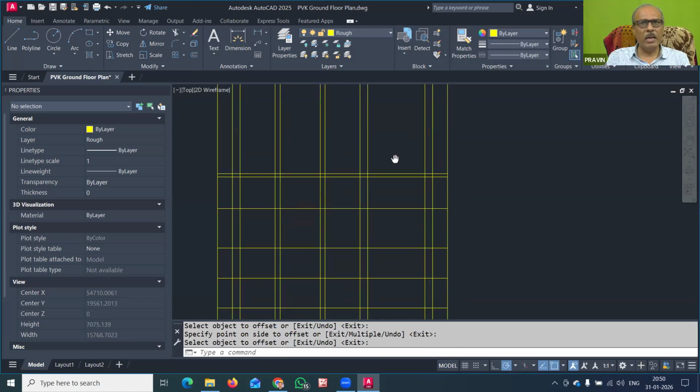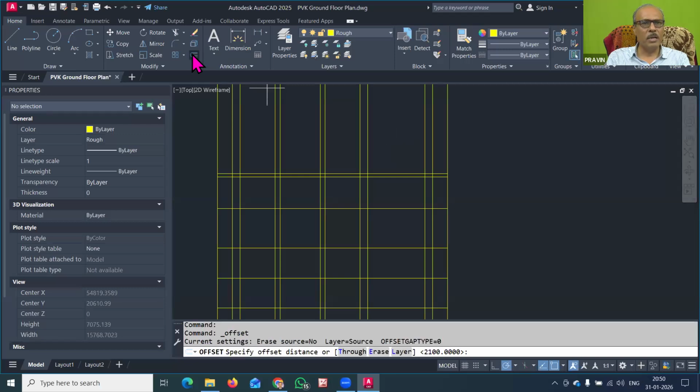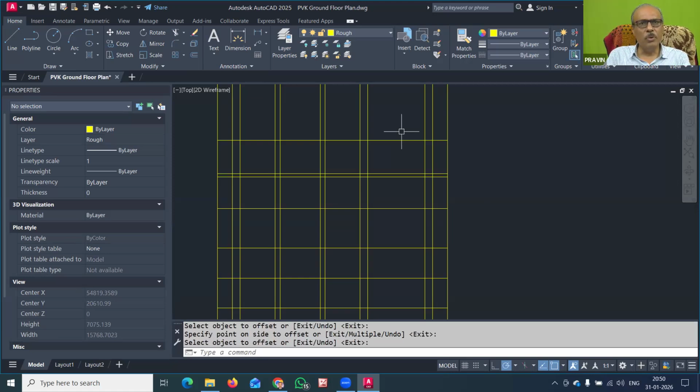Instead of that, again you require to show the parapet. The height of the parapet you can take as 1 meter. So you can offset, it may be generally 900 or 1000. In this case, we will take the parapet height at 1000. So we will go here and I will offset this line 1000 for the parapet. Now this way your grid for the building elevation was done.